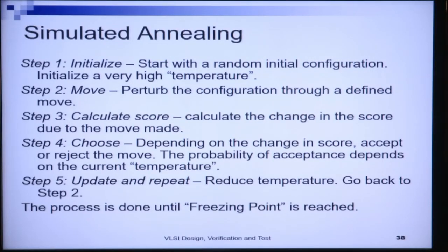Now from that initial configuration, I make moves over the state space. At each move, as I said, I either merge or split. With that merge or split, where do I go? I go to another merging of the temporary registers and operations to obtain a different allocation of the functional units and registers, and we will have an associated mux and demux cost. Due to that move from one state to another, in the new state I will have another cost of the solution.